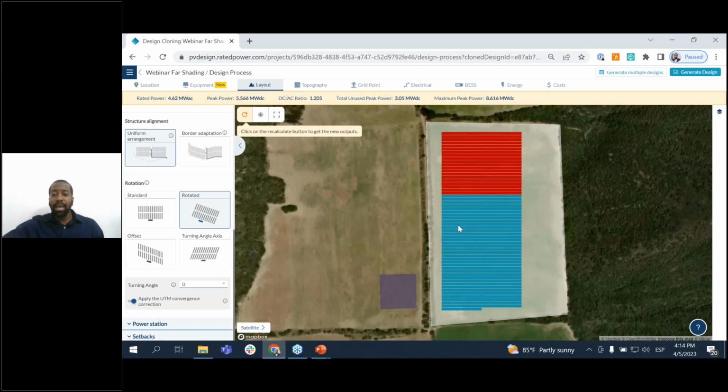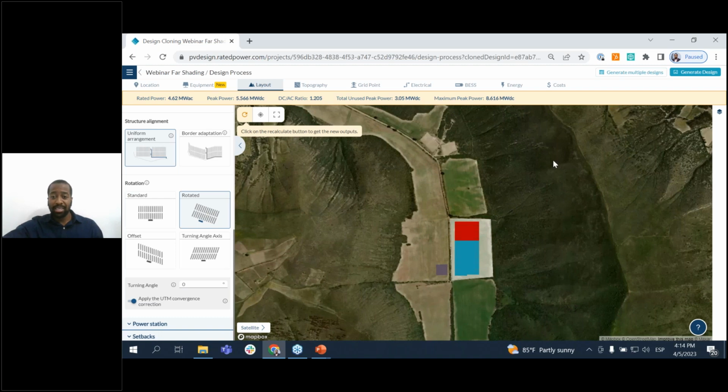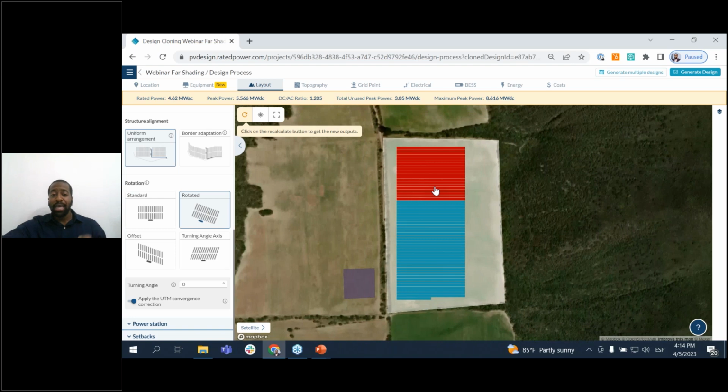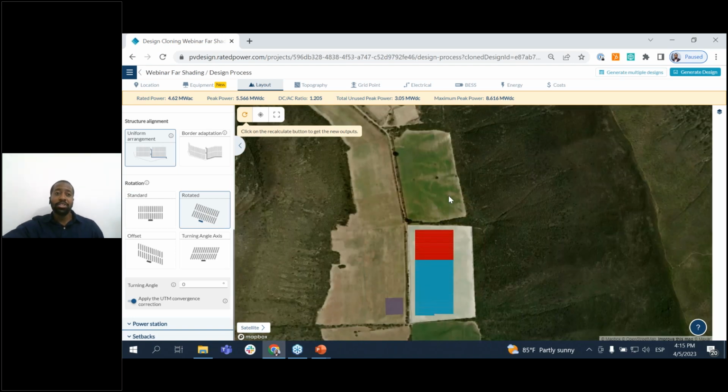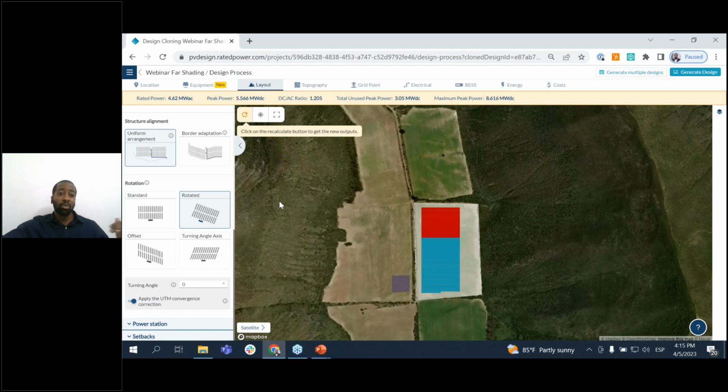So if I have a lot of shades from the east side accounting for these mountains, and I have my panels facing north, then the ideal case would be to have them oriented or rotated towards the north and the west side, right? Because on this specific side we have a lower elevation, and so we should be getting more light from this side. So I'm going to run 3 different iterations, changing this azimuth so that we can see how it is actually affecting our energy yield.